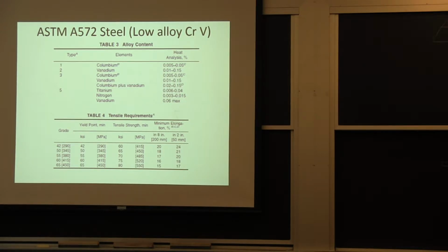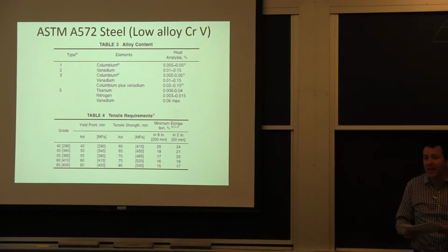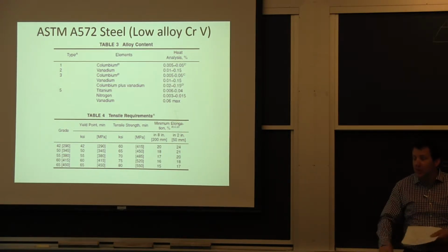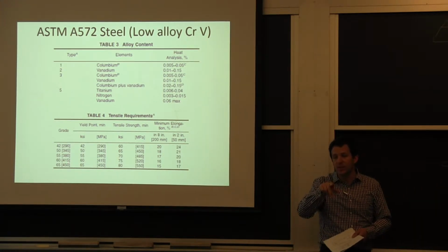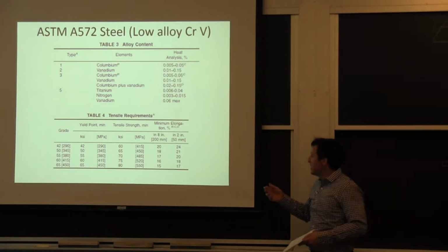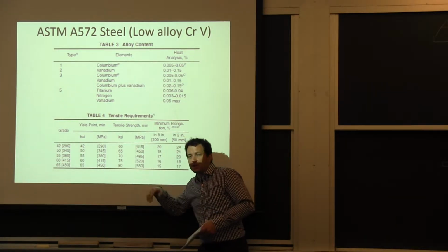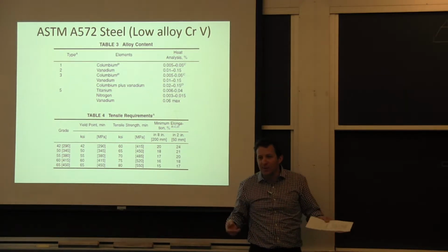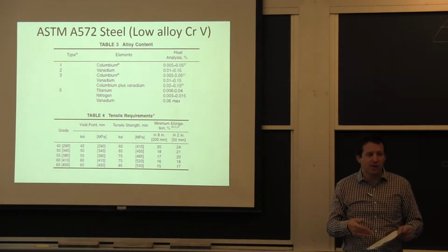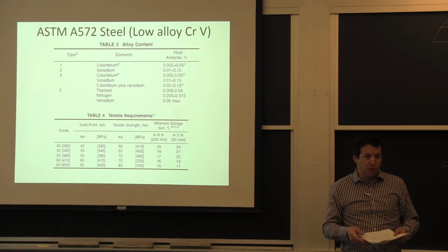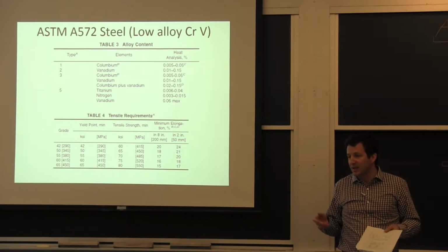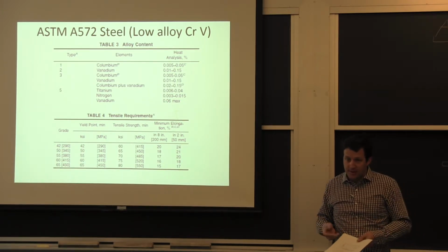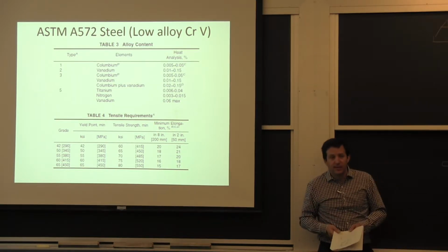The ASTM specs are 10 pages, and they call for other specifications in terms of basic requirements, how you're supposed to measure stuff, how you come up with these properties here. If you saw that dog bone sample, that's part of this. This is not something where I machine a sample the way I want, get the number, and say, oh, it meets ASTM. I need to run the test the way ASTM wants me to run it for that specific shape. So there's one ASTM spec for testing steel products. If it's a wire, it's different than a plate. It's different than a sheet.